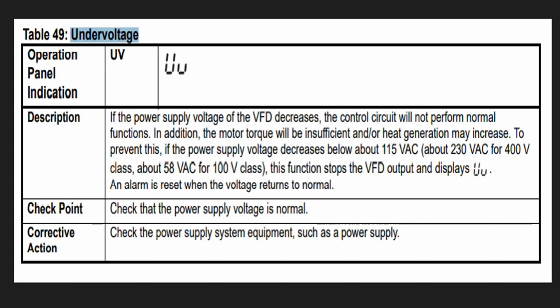So to resolve this alarm you can check all these things I told you, and hopefully with these activities your problem will be resolved. And at the end, if these are not the problems, you have checked the input supply, you have checked the connections are properly connected, and still the problem is the same, you can contact for repair, and after repairing this VFD could work.